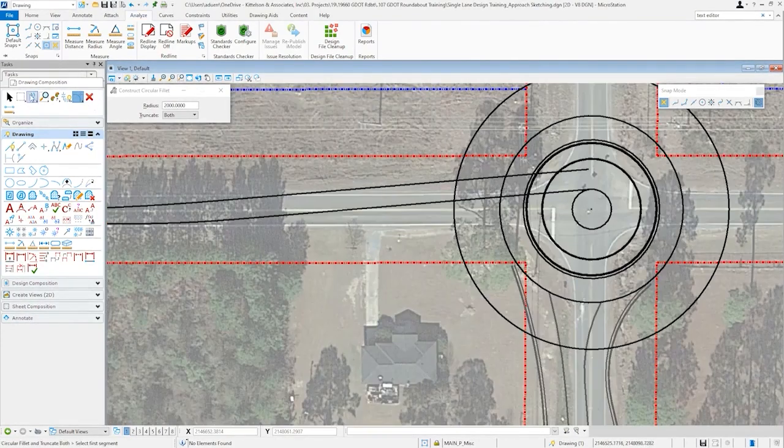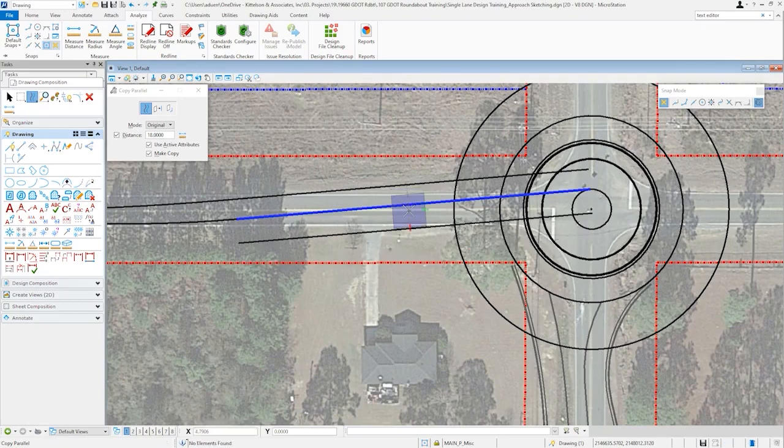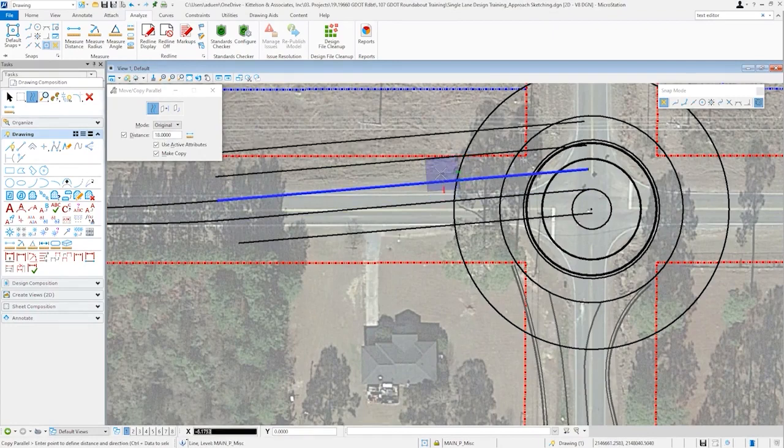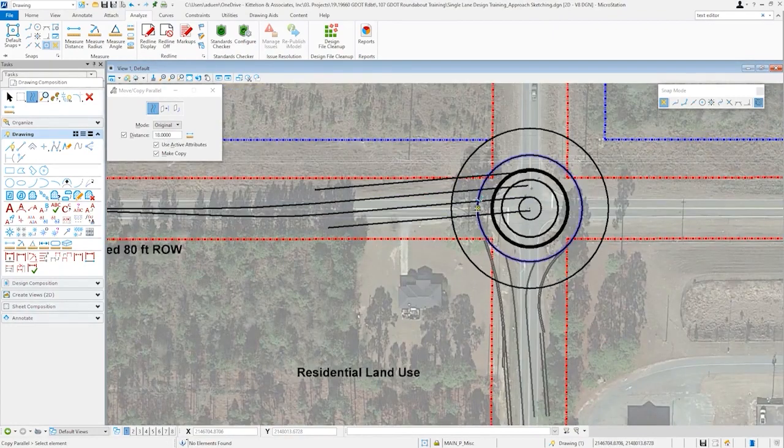So I'll begin by offsetting this line 18 feet with the 2-foot curb and gutter on the outside. That will give us 20 feet to this painted line, and then there'll be an offset to the splitter island. So we'll have that 18 feet gives us that 20 to 24 foot dimension that we're looking for. We'll offset the exit side as well.